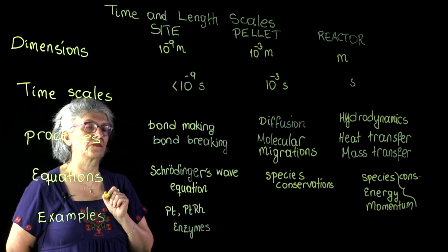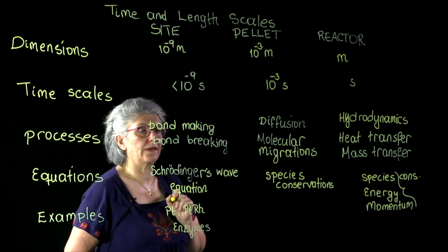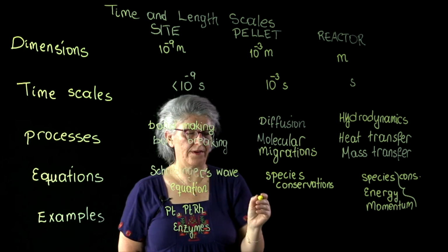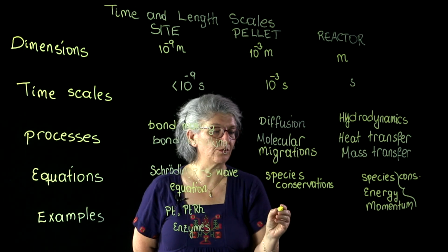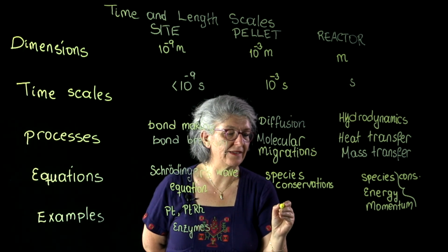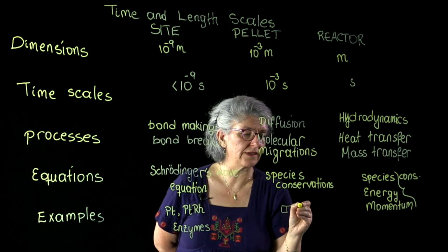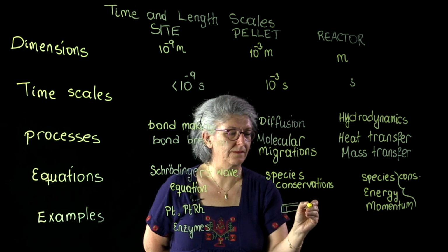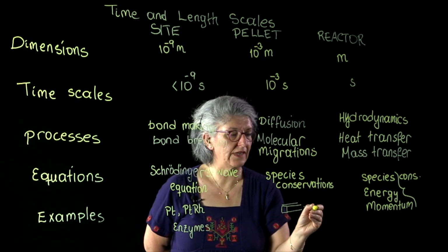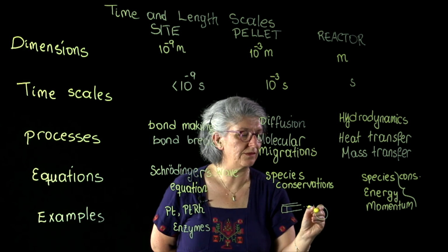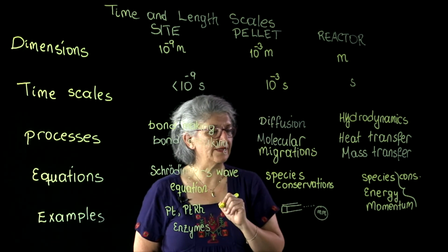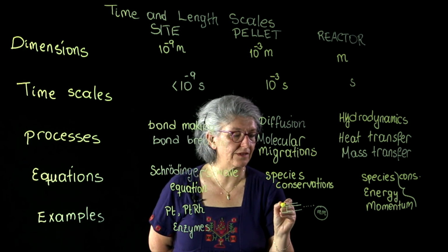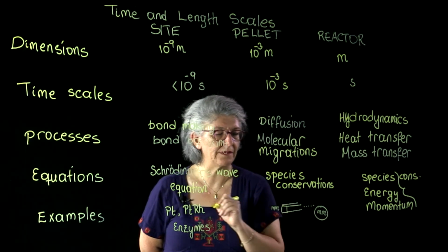A typical pellet is the monolith, where you have those platinum or platinum rhodium catalysts. It has millimetric openings, a multi-channel system, or it is a spherical pellet which has a millimetric diameter with impregnated catalytically active materials. So we have millimetric scales.